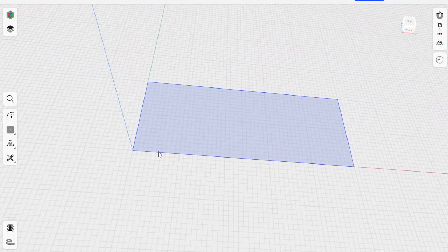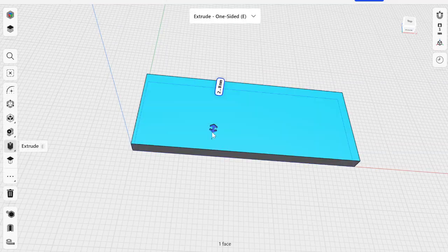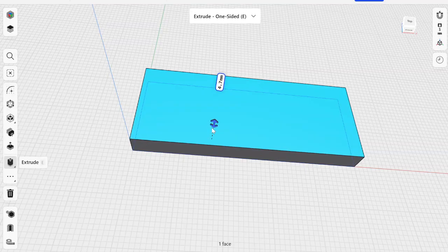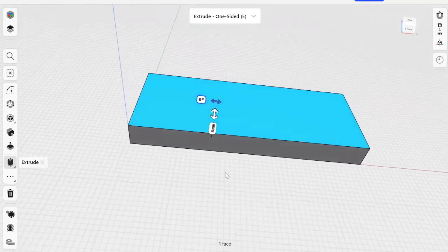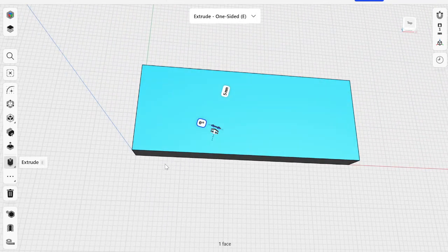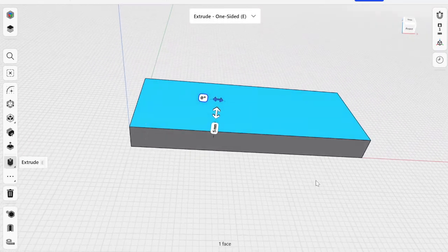All right, so once I've got this shape, if I want to extrude it, which is the term for adding depth to it, click and then grab the arrow and I can pull it up. And I can even type a number in here to make it 5mm. And I've now got this 5mm rectangle, which was 5 cm, 2 cm, and then half a cm of height.